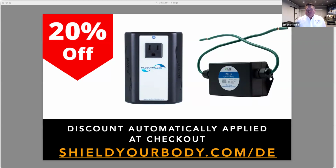And that's just a notorious cause for dirty electricity. Now if you use a filter, you're going to exacerbate the problem. One of the writers had asked, hey, I've got a Satic and the number is still really high at the wire end. I can almost guarantee it's a bonded neutral ground issue. The way we wire homes and using 60 hertz and all that is a completely different conversation, but working within the framework that we have, making sure that at sub panels the neutral and the ground are not bonded, not bonding those whenever you can code wise, making sure that all of your outlets are wired correctly.